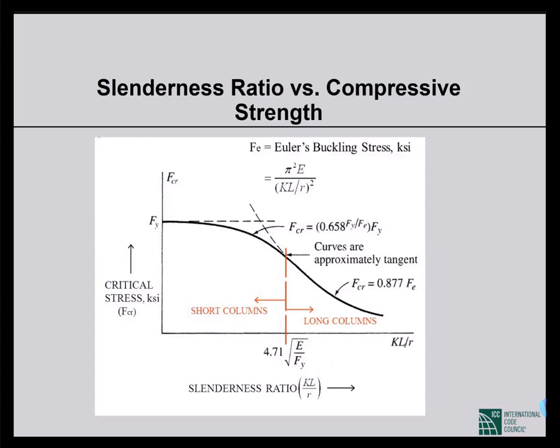That is a very good case. We can use up all the material up to its yield stress. This is the maximum capacity a section can have, and that is called plastic capacity. In terms of moment, we call it plastic moment Mp.